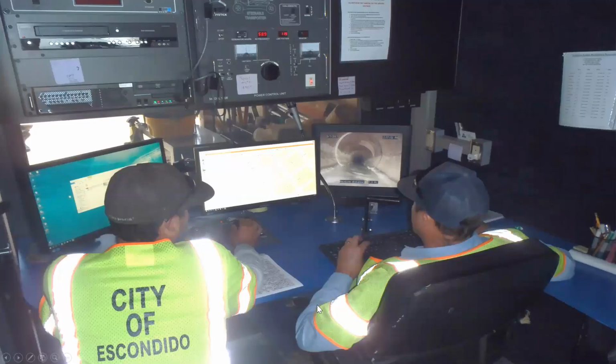Now, this is my favorite slide of the entire presentation, not only because it reminds me of televising with Kyle and Josh, but most importantly, because of the significance of how we got those PACP results. For those of you on the call who may or may not know, these are entirely dependent on the quality of the PACP defect coding.